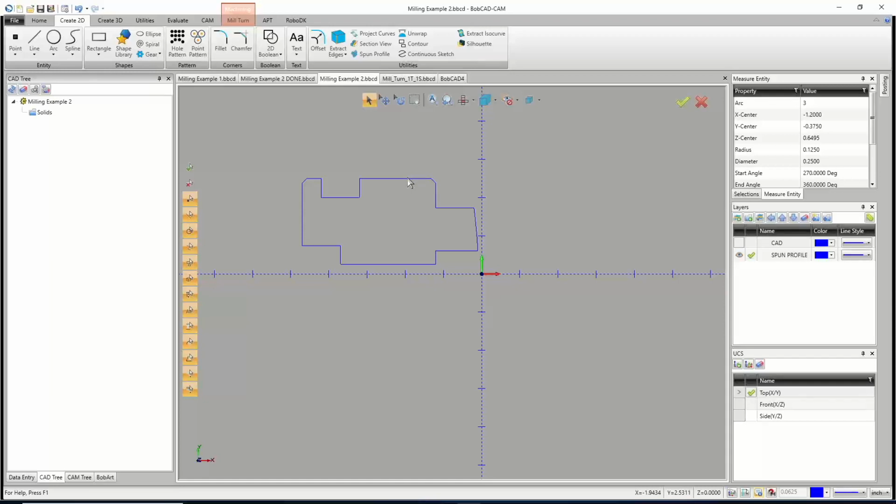If you really want to understand that, the best way for me to put it is it's all based on the midpoint. So if the middle of the line is here, if I move to the right, hold shift and click, I'm actually sending the chain to the left. We always send the chain in the direction that's the longer side of our click.